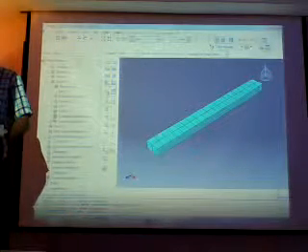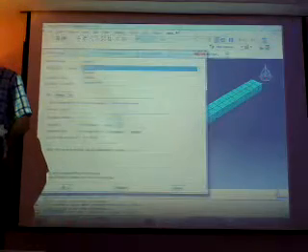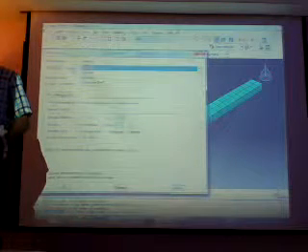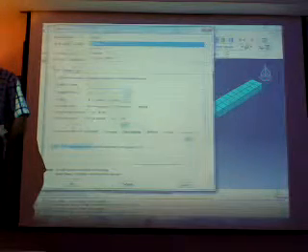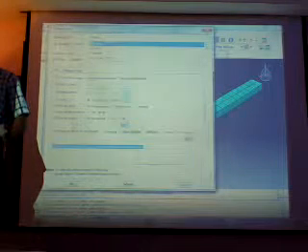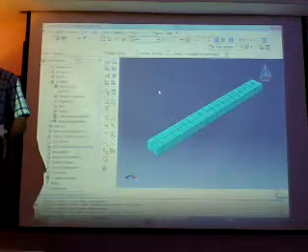Here also we have another important icon, assigning element type. Here, as you can see, we have standard and explicit. If your simulation is explicit, that's important to take explicit one. Now our simulation is standard, so we take standard. And your mesh type mentioned here. Our mesh is 8-node linear brick, reduced integration, hourglass control. That's okay. And there is another options here. Keep them as a default. And okay.